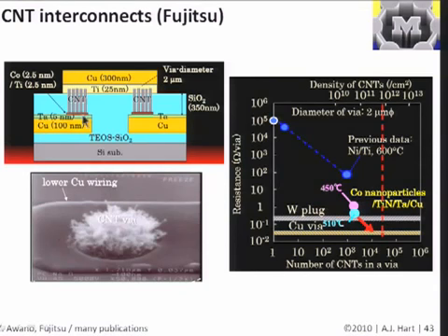They deposit those and grow the nanotubes on these small areas of catalyst, then fill the whole area with silicon dioxide, polish that down, and put down a top contact. They characterize these by measuring the electrical resistance through this path.